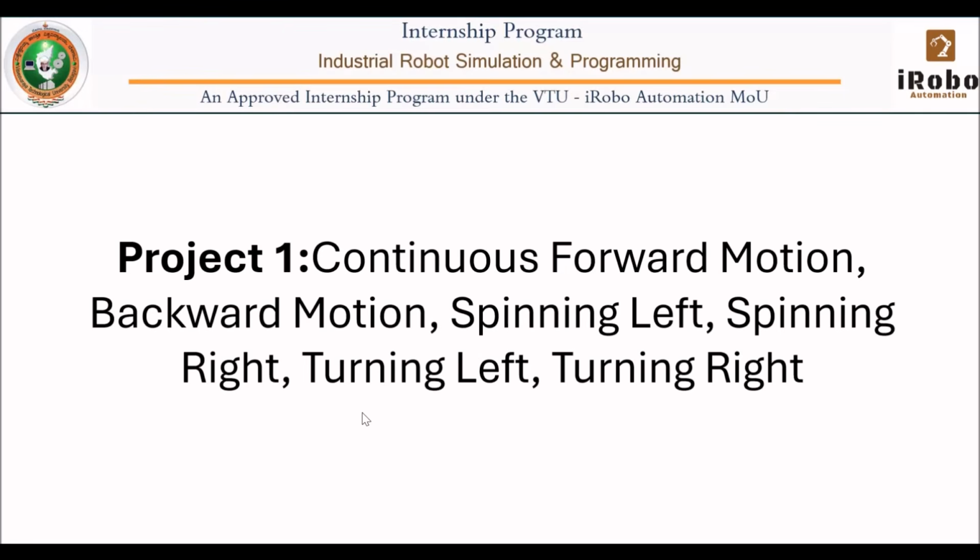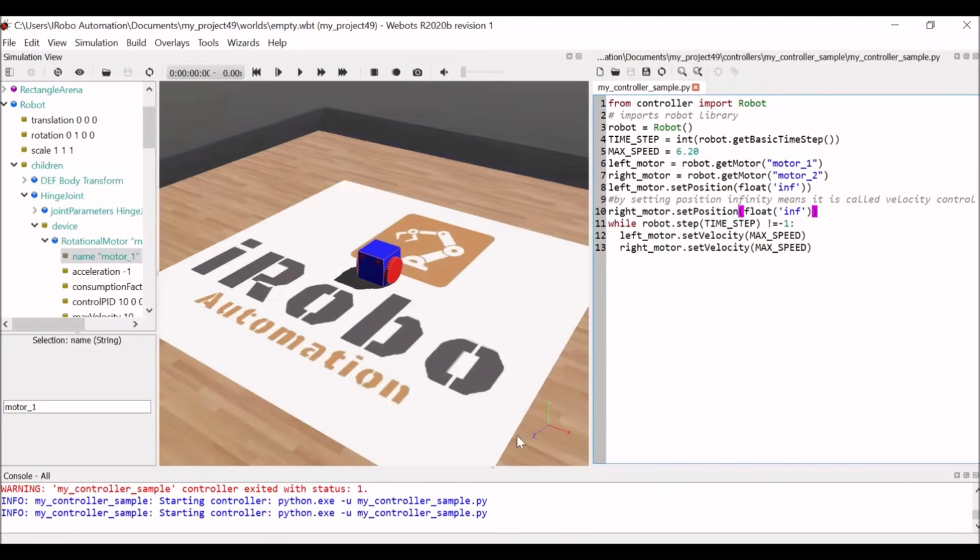So now how to move the robot backward? So for that I will make a minus here. Both left motor and right motor both are negative. Velocity is a vector quantity, right? So I'm changing the direction here and save it. Save the program and then run. It's moving backward. Okay. Again, stop, reset. So this is how we can achieve the backward motion.